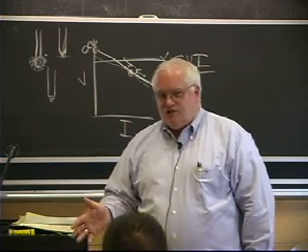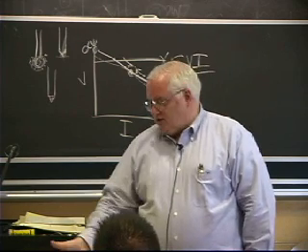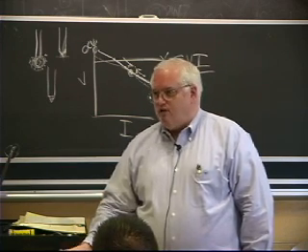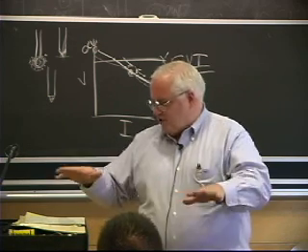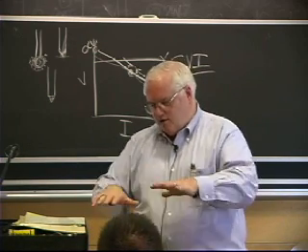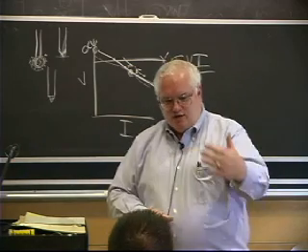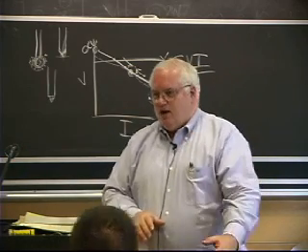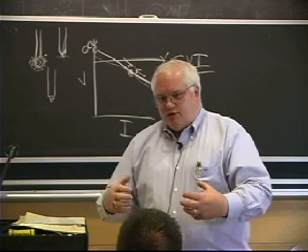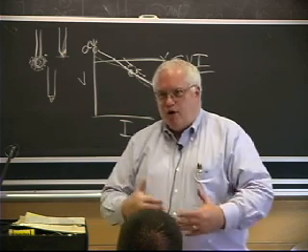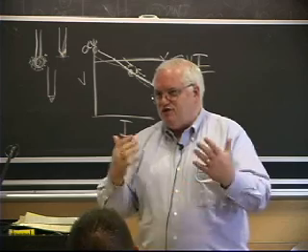And there was enough resistance in the concrete, because concrete's not a good conductor, right? Basically enough power was going into the ground that it started heating, and you now have 13,800 volts on the sidewalk, and that's all got to be dissipated into the surroundings. Well, right next to the sidewalk was the brick wall of this old mill building, and supposedly it had some file cabinets up against the wall, and there was arcing going on between the wall inside the building and the file cabinets. And this eventually started a fire.